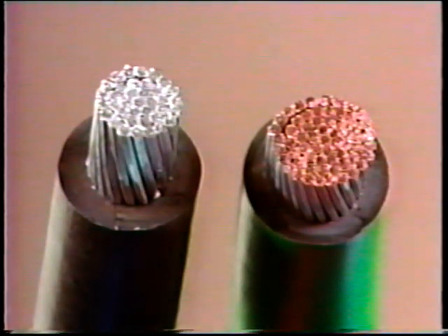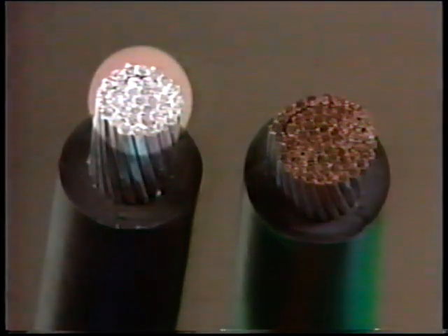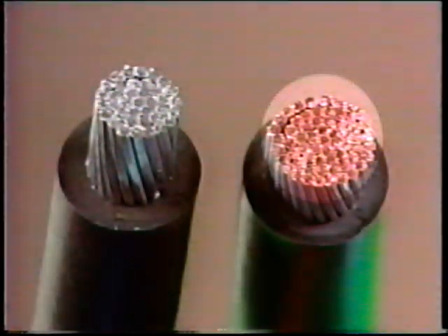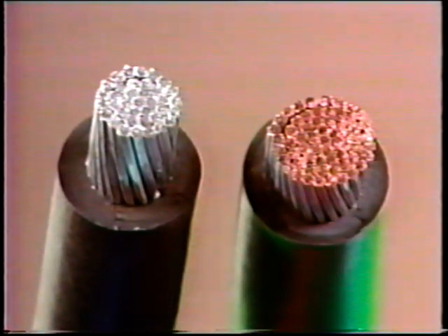Now, here are some samples of conductors that are sized according to the circular mil system. This is a 400 MCM conductor. This one's a 500 MCM. As you can see, as the circular mil size designation gets larger, so does the conductor. Well, we've covered the two systems that are used to designate conductor sizes, and we've looked at samples of each. Let's take a general look at the second thing classification is based on: types of insulation.